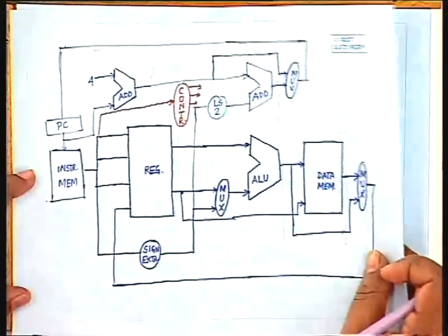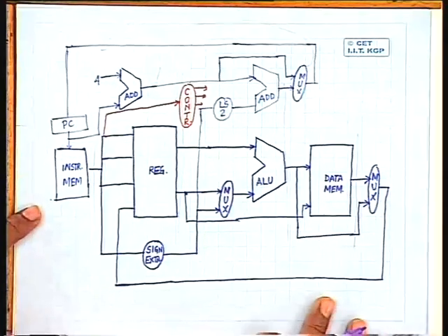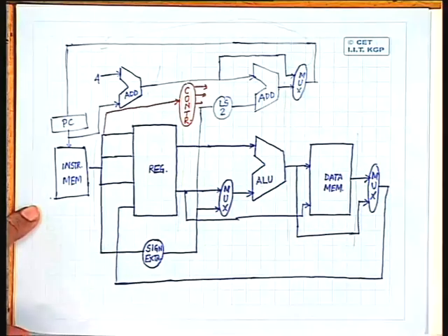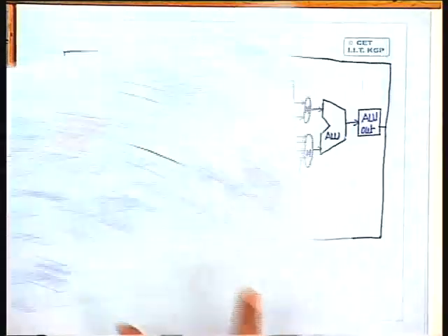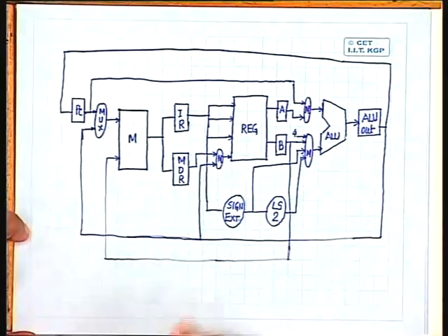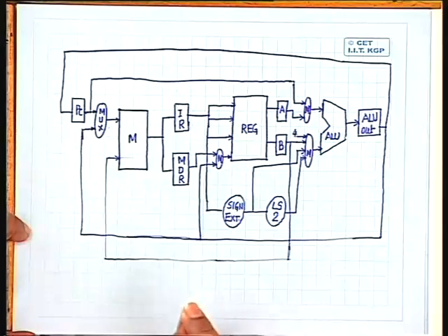our earlier case, the basic design was suitable even for a single clock period execution. Every instruction could be executed in a single clock period in this basic design. Okay. Now when we converted this design to this design, now we can make use of multiple clock periods to execute an instruction. And what is the advantage we gain? That is, even the instructions which require shorter delay, that can be incorporated. So the CPU will be more efficient.